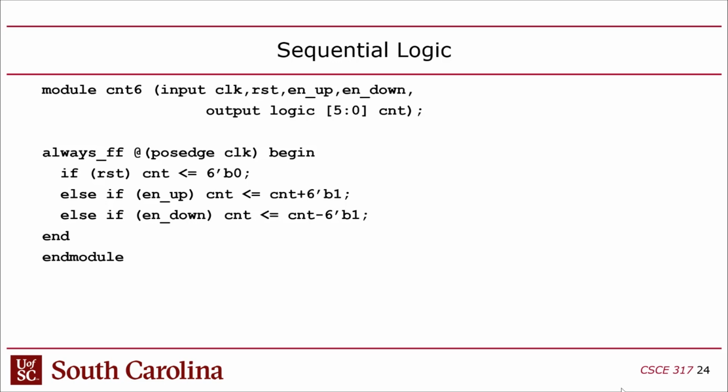We used to have a project in the first version of this course where we did bit banged UART. You wrote Arduino code, on an Atmel 328, that would do UART with bit banging. That was kind of cool, because we plugged it into the computers and it would actually send characters to the screen of a Linux machine. I thought it was kind of neat, but it's not very practical.